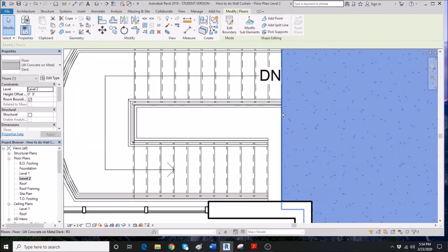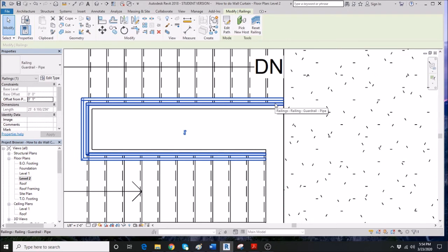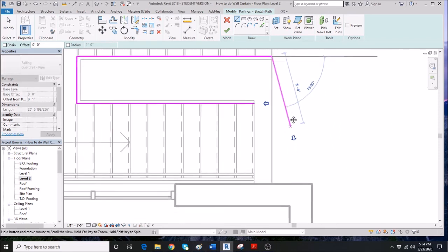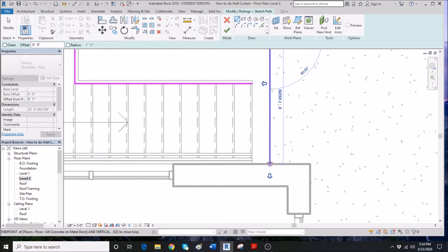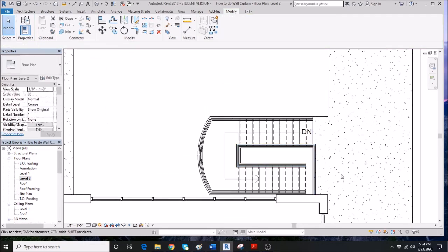So we are going to create a connection from here to here as well too. So we will be creating an edit. So I want you to click this one here. So we're going to add edit pad, and we are just going to add pretty much the way that we did it on the back stair as well too. So connect that and then click OK. All right, so that is now your stair here already.